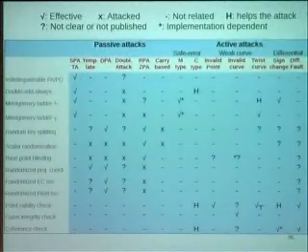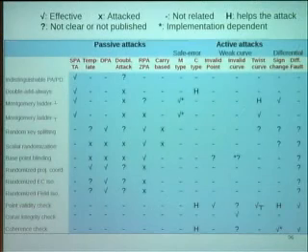But you see, this algorithm is not good against fault analysis, because you inject the fault in the addition operation. If the result is correct, that means that operation is a dummy, which means that the key bit is 0. So this countermeasure is actually helping another attack. And if you look at the whole table, you see quite some of them. The H here means that this countermeasure is helping another attack.